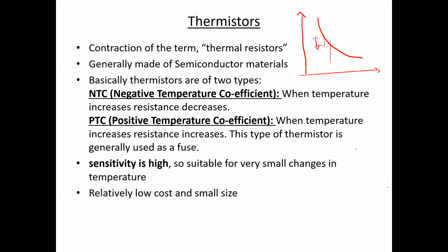So for small changes in temperature, the change in resistance is high, so the sensitivity is also higher. And compared to RTDs, another advantage is that they are low in cost, and as they are made of semiconductor materials, their size is also relatively smaller.